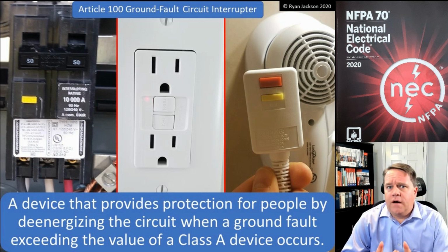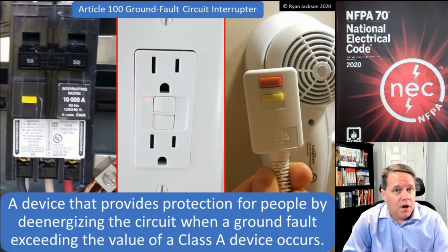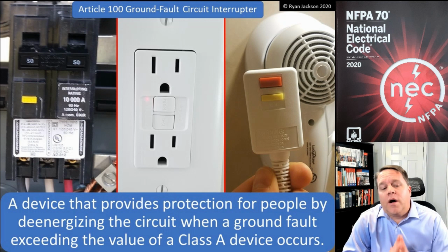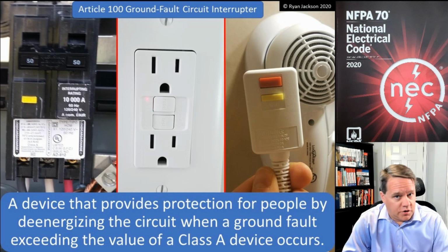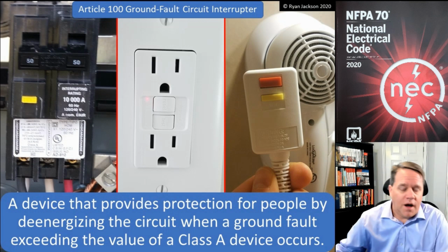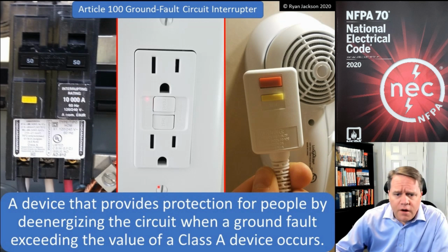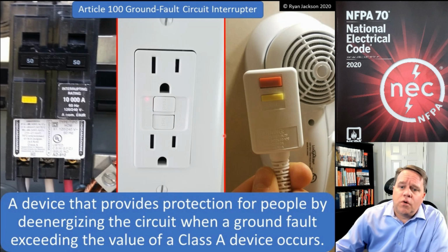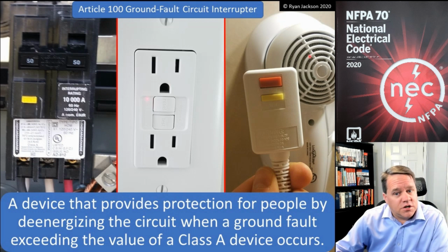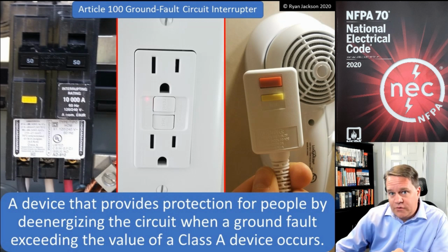So what is a GFCI? Well, it's a device that provides protection for people by de-energizing the circuit when a ground fault exceeding the value of a Class A device occurs. From left to right, we've got a GFCI circuit breaker. Here in the center, we have probably the most common type, a GFCI receptacle. And over here, we have an integral GFCI in the attachment plug of this hairdryer. Those are all three different examples of GFCIs.